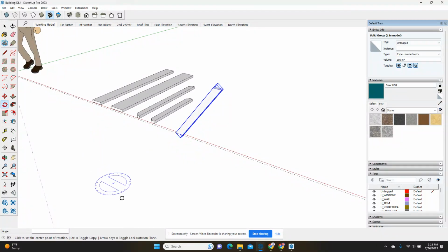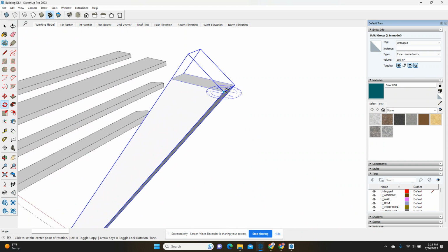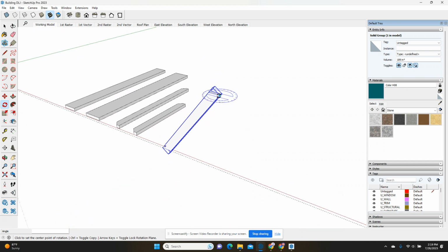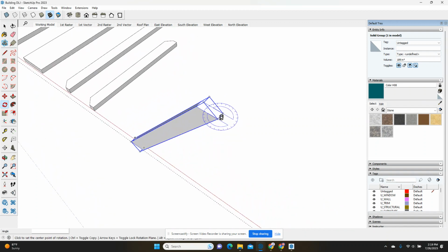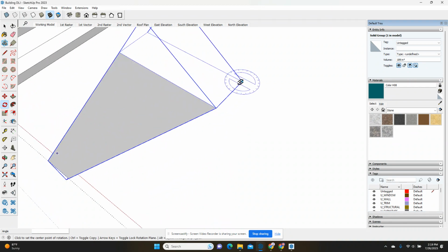Okay? Now, the picnic table has a leg going up this way and then back down this way. And those two legs meet right here on this edge. So what I'm going to do is rotate this so I'm looking kind of down at the top of it right here. I'm going to find the midpoint of its thickness right here by sliding along here, and it will tell me midpoint in group. With my blue protractor, excuse me, I'm simply going to pick right there.